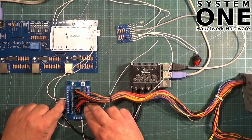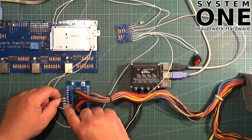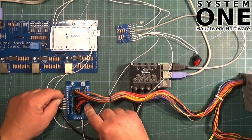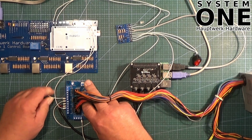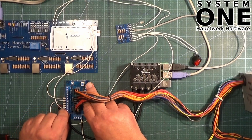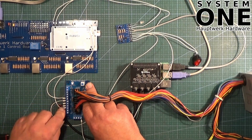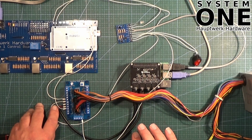Also, all of the wires, I like to put these little ferrules on. Again, you can get these really cheaply from Amazon. These screw connectors I don't think are the most reliable things in the world, but if we put a ferrule on the end of each piece of wire, then that makes everything stronger and more robust, and there's no way that wire is going to pull out. Those little kits for doing this come with some ridiculous amount, about 12,000 ferrules or something, or maybe it's 1,200, I don't know, there's a lot of them anyway, and quite often they come with the tool for fixing these onto your wires, so they make it look more professional and they make it more robust, in my opinion.